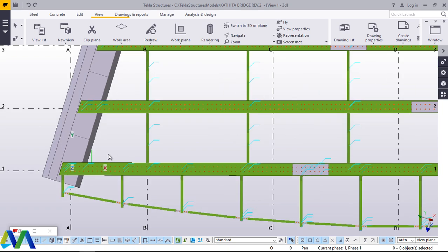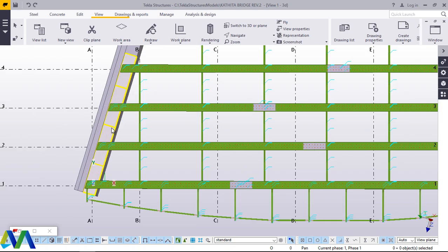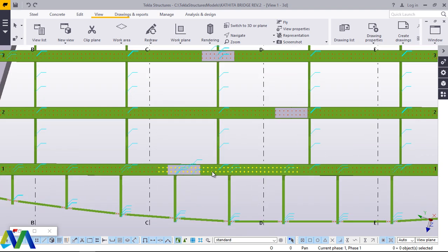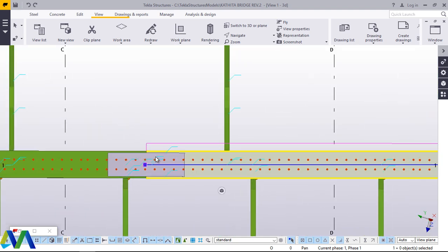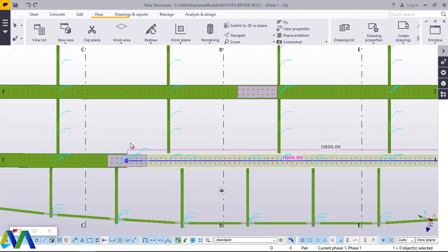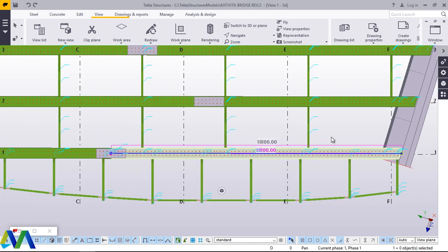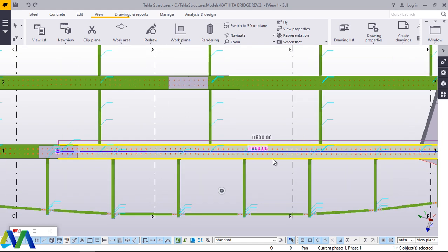Now also, if you take a look here, one side of the beam I made a full height of 1100 because we don't require a lot of wastage of the beam, since they are sold in 12 meters length.